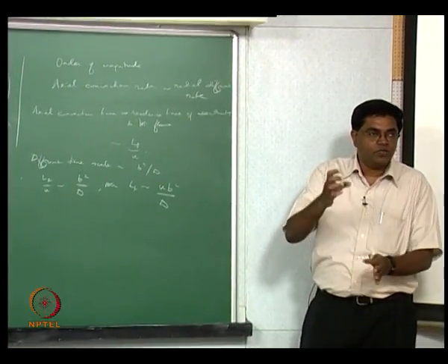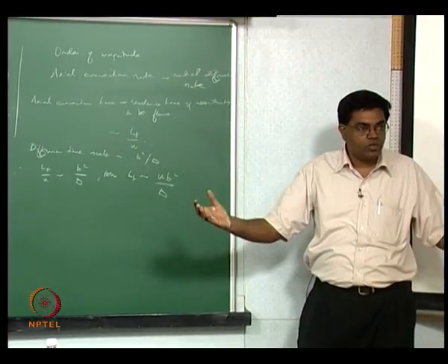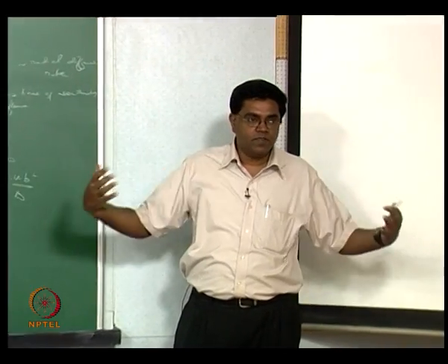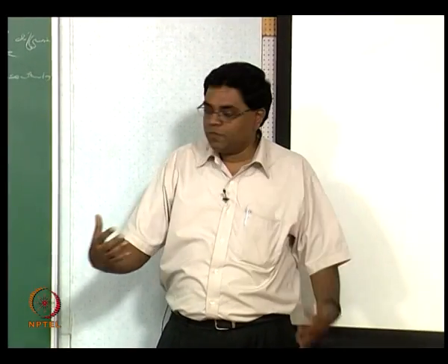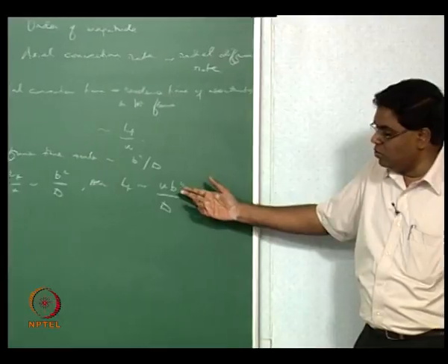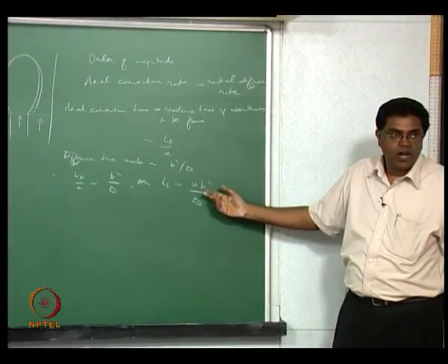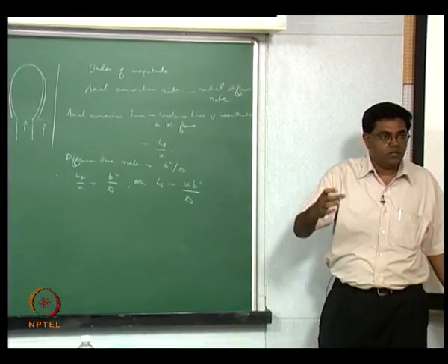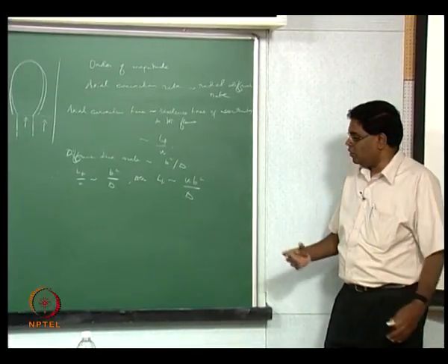So in a jet diffusion flame you have only one duct, you don't have the outer duct. It's just entraining and diffusing with atmospheric quiescent air. Therefore you could simply say U small d squared divided by capital D, where small d is like the diameter of the jet, or the inner pipe.